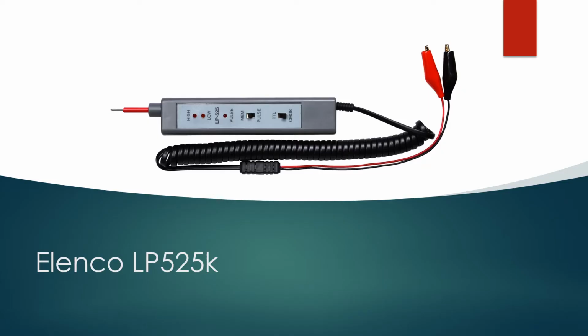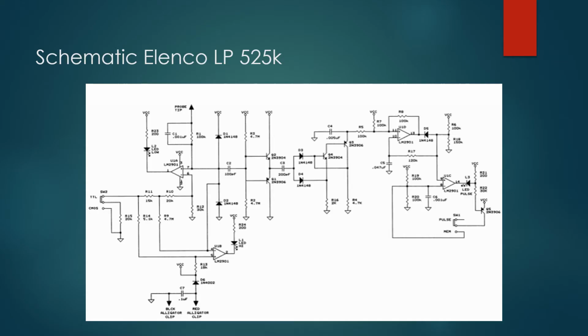Well, I am going to explain about two probes. The first one is Elenco LP525K. As you can see, the schematic of the probe is fairly complex. It displays logic levels high or low, with voltage transients down to 25 nanoseconds. The LED readouts provide instant response to the logic state.